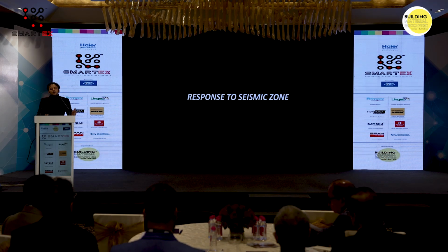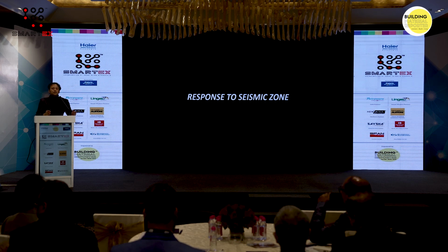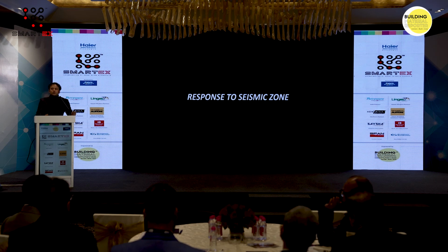Now in terms of seismic, because earthquake zone 5 is one of the most harsh zones to design, given the movement, for this we had Miyamoto International doing the structure. They were doing drift analysis and ground acceleration analysis for us. It is a little different because Indian code, so usually Nepal code refers to Indian code for structural guidelines. In Indian code, zone 5 is defined as complete and utter destruction. So there's no guidelines for zone 5 in Indian code. That's why we had to change the way we designed this building in zone 5. It was all about acceleration and drift. And based on this, the structure and the facade was also designed.